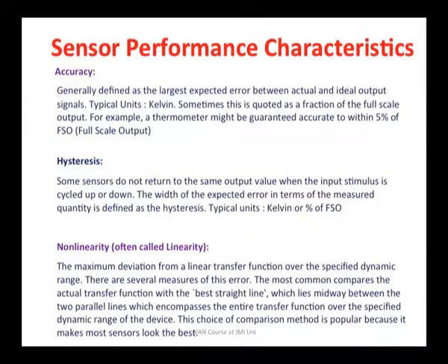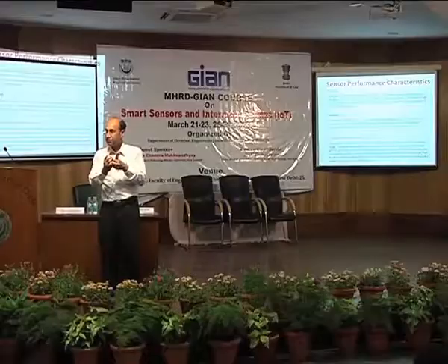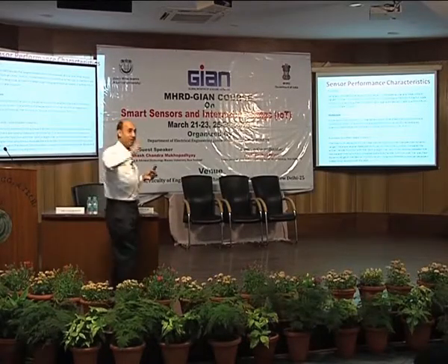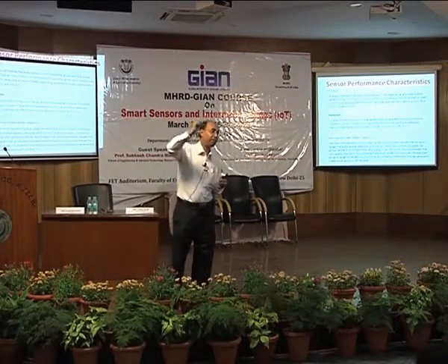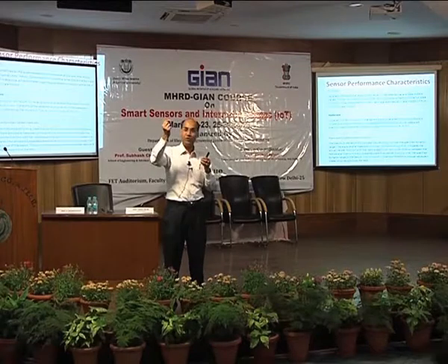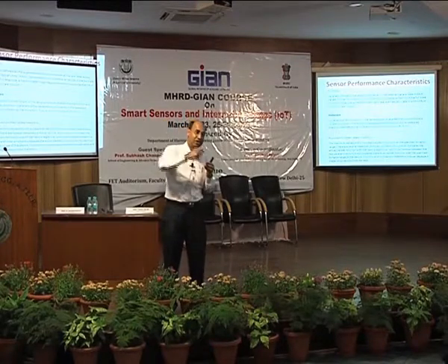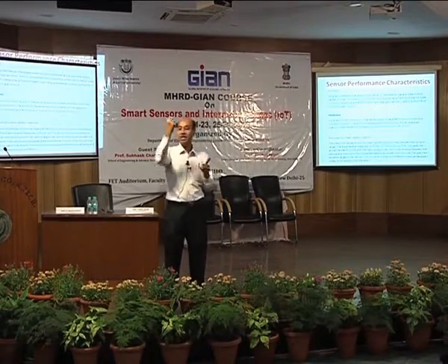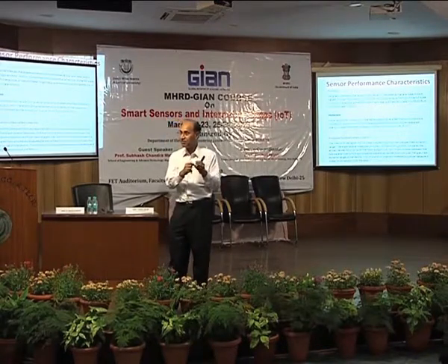If it does not follow the same path, that means it kept some history in its memory, and that is reflected in the output, and that is dangerous. You understand? Because at some particular application, corresponding to 30 degrees centigrade you got some value, but then when it is decreasing, you get a different value. You do not know. You get the value, and that decides the temperature.